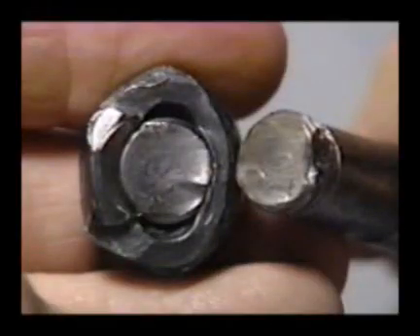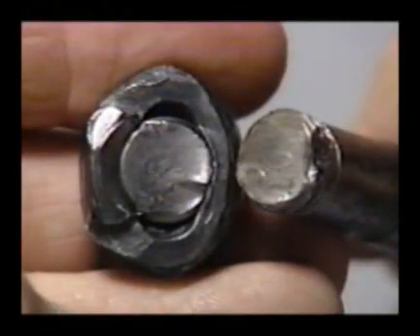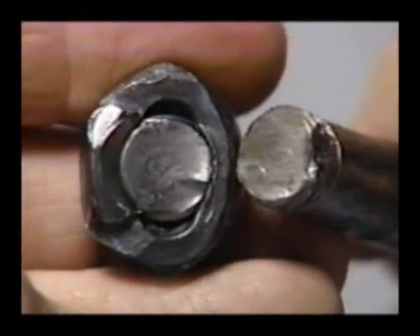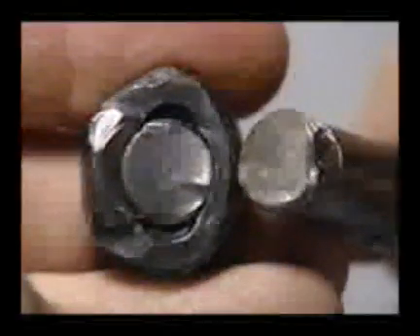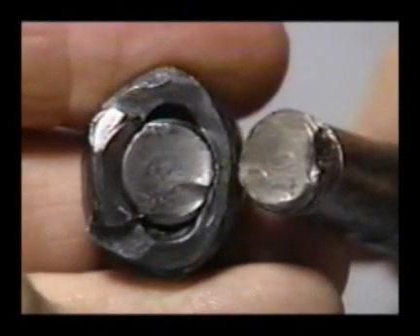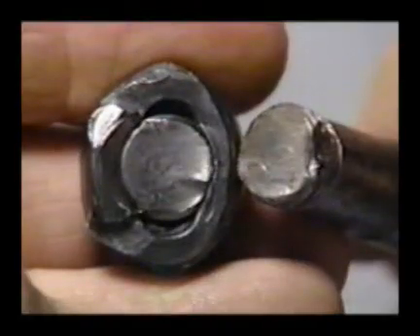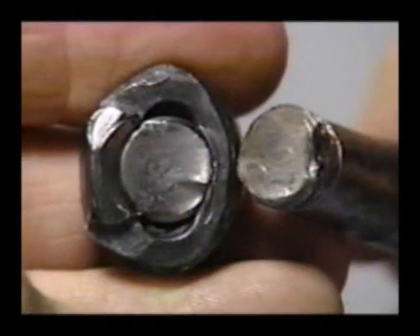If a part is subjected to a direct shear load, the fracture starts across the entire surface at the same time. As the fracture surfaces slide against each other, they wipe out the fracture detail, leaving a smooth, silky appearance.